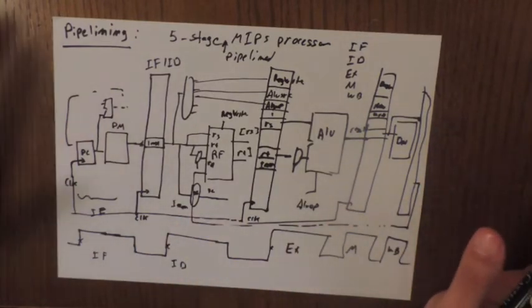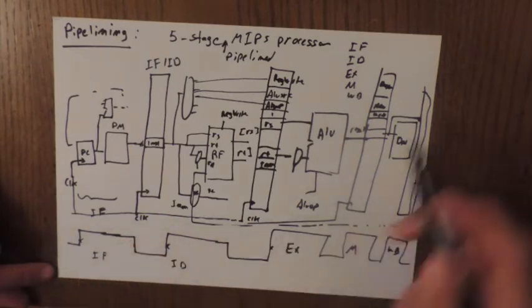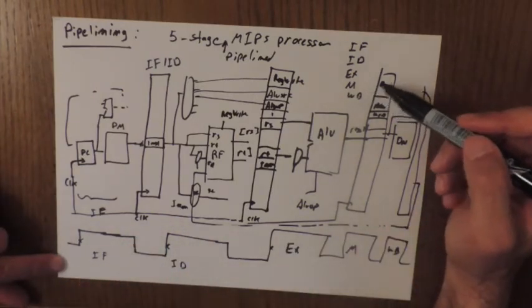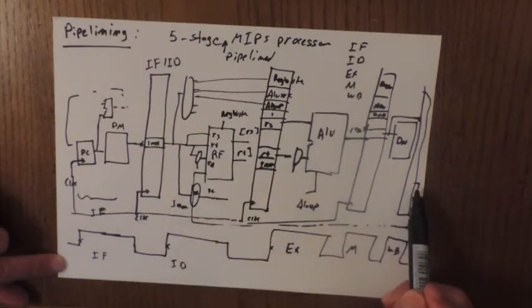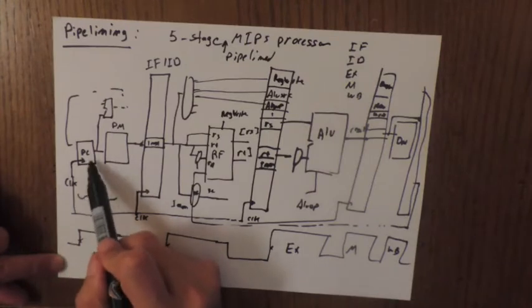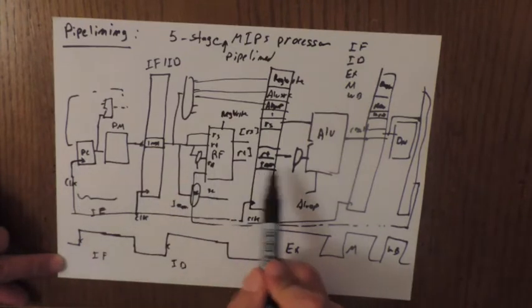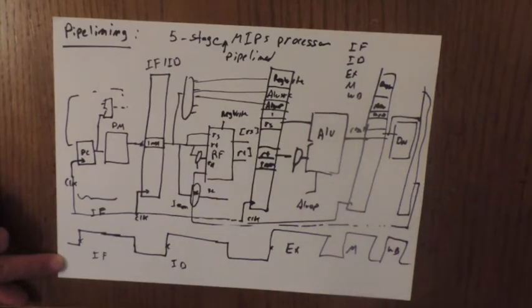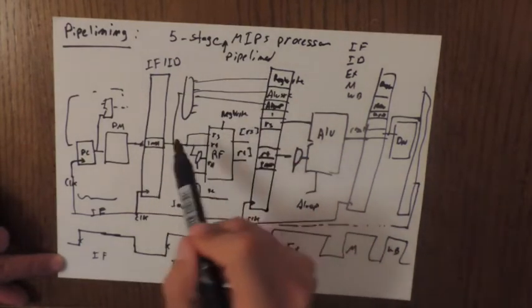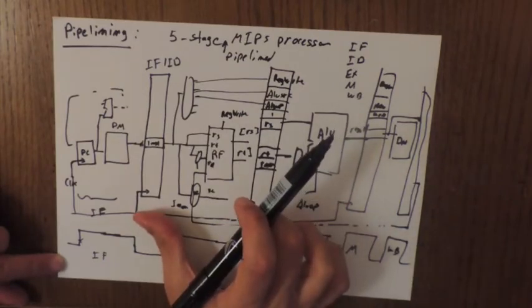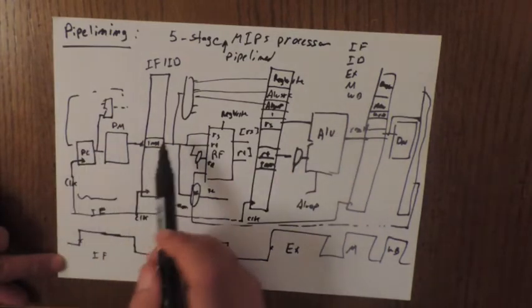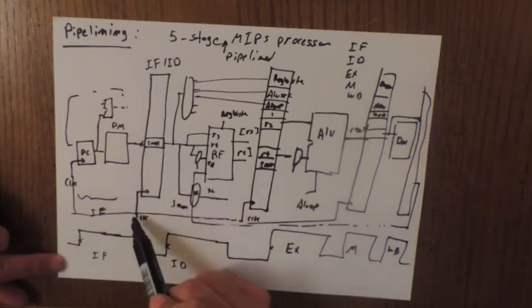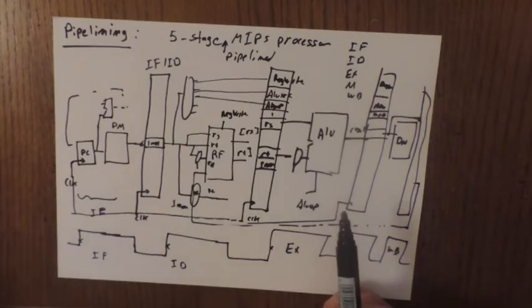So the main idea I want to discuss here is that the way we impose a 5-stage pipeline processor is by including 4 pipeline registers. Of course, the 5th stage comes from PC, because it's clocked. So this is 1, 2, 3, 4, 5. So we have 5 sequential elements, and inside these sequential elements we have a combinational circuit. This combinational circuit will only change value after the input value is changed by a rising edge on the clock cycle.